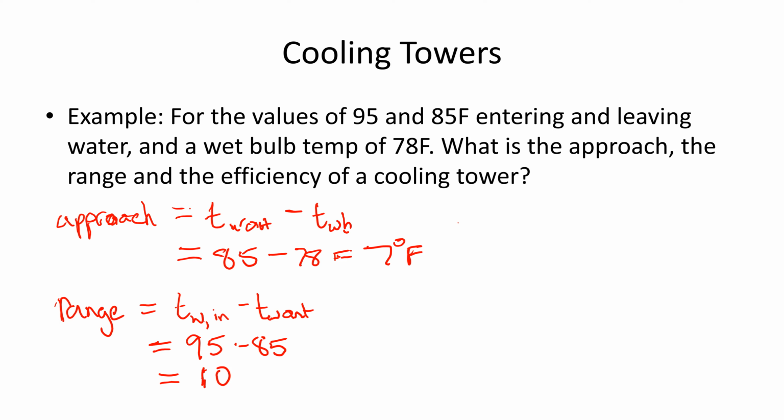If I go to calculate the efficiency, remember that it's going to be my range divided by my approach plus my range.